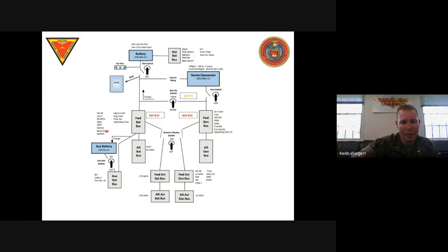I've got my starter, right? The whole starting relay itself needs power because it's going to draw that power from the battery. The electric boost pump itself, remember that comes on whenever we're starting the plane. And I've got the igniters, right? The igniters are just the giant spark plugs in the combustion section of the engine that are going to light your fire whenever that fuel is in the combustion section.